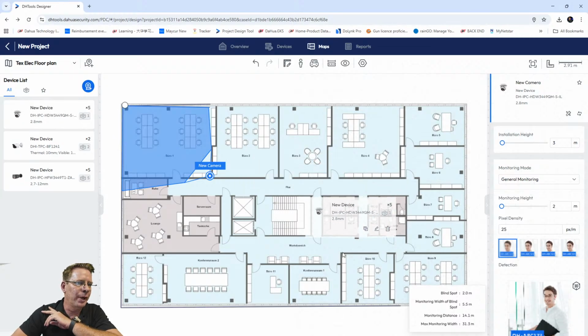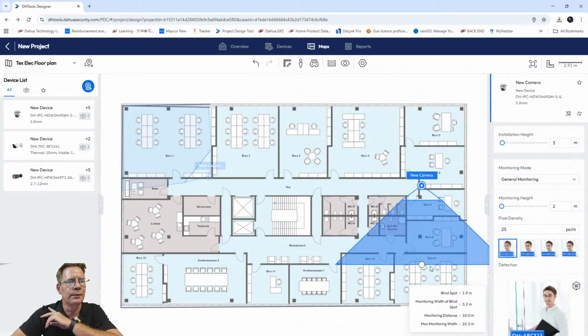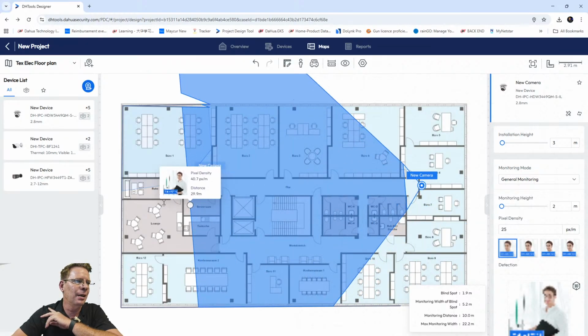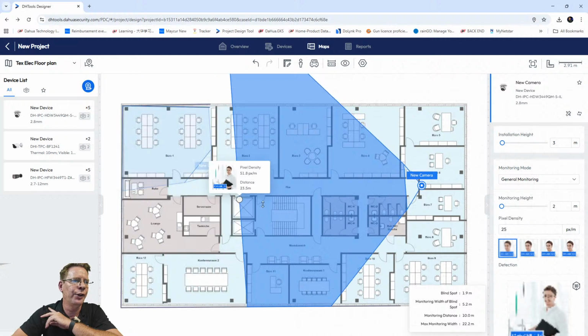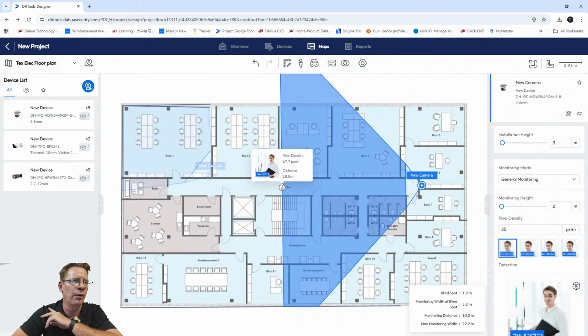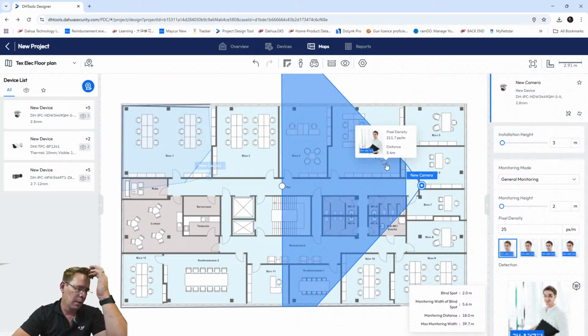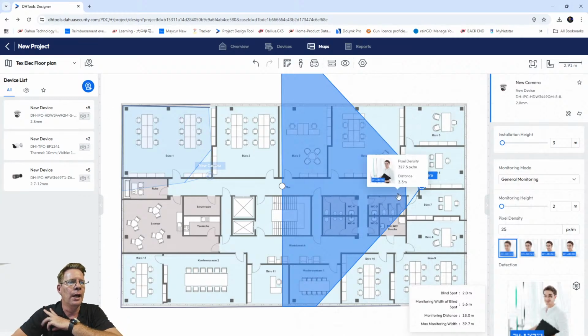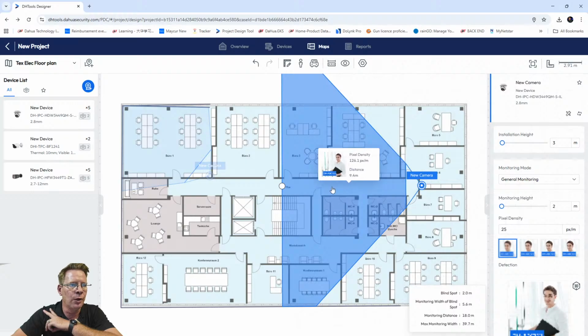Then I'm going to drag and drop another camera. So they're looking for a camera here in the hallway. So I'm just going to put a camera there. But obviously, in this area, I don't want to go for a 2.8. So I'll rather change my lens size to a 3.6. Because the 2.8mm lens, to look in this pathway or in this area, it's too wide for it. So rather go for a 3.6 or a much higher lens size camera to use in a passage.